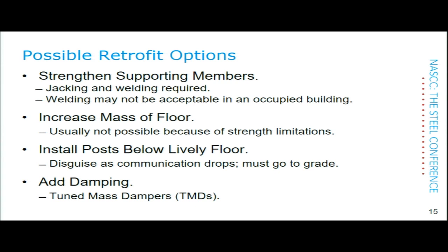Many times it's possible to install posts below a lively floor, especially if it's the same tenant. The posts have to go to grade. I realized this one time, I suggested posts between two floors. Couldn't go to grade because there was a parking garage below it. And the next day we took the post out because I had doubled the problem.